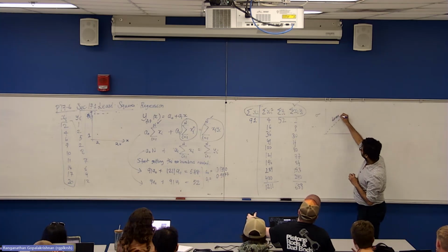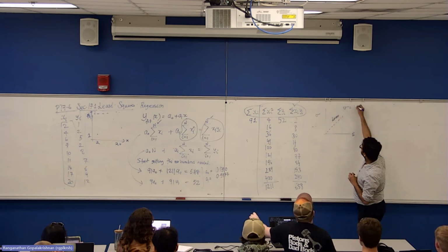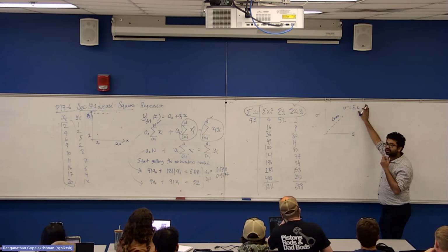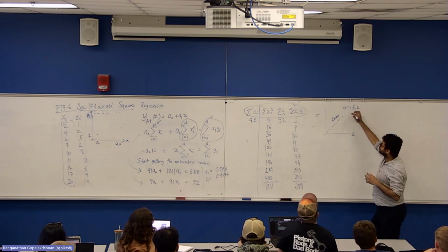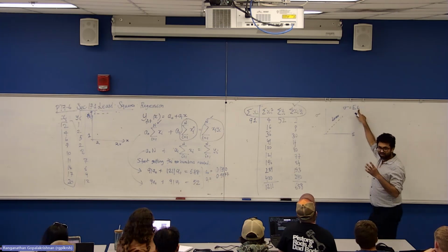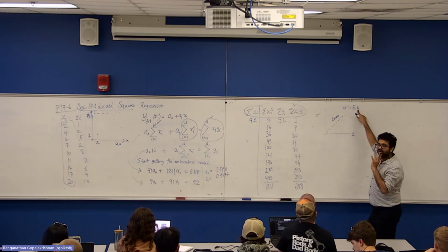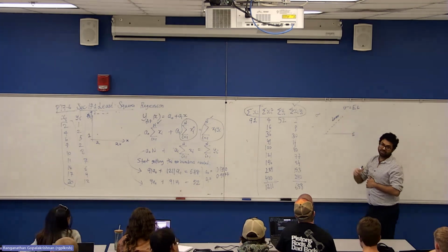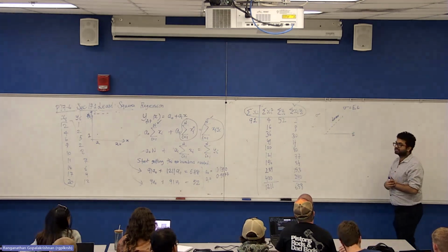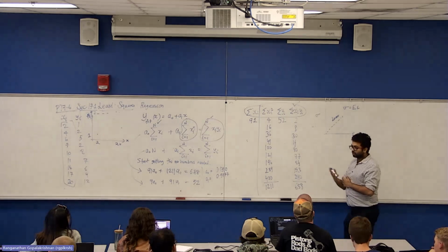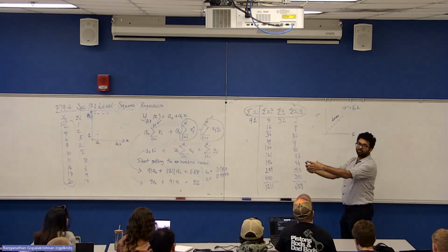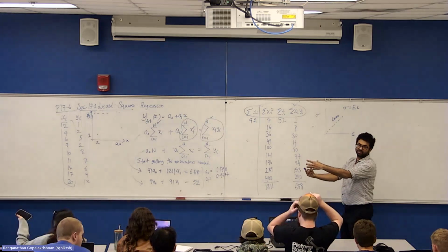So we would essentially have sigma equals E times epsilon. And in the lab, what quantity will you actually be measuring? Stress and strain are kind of theoretical constructs, but what is the raw data that you will be measuring? You're doing tensile testing. Load, right? You hang a weight on a component and see how much it extends.